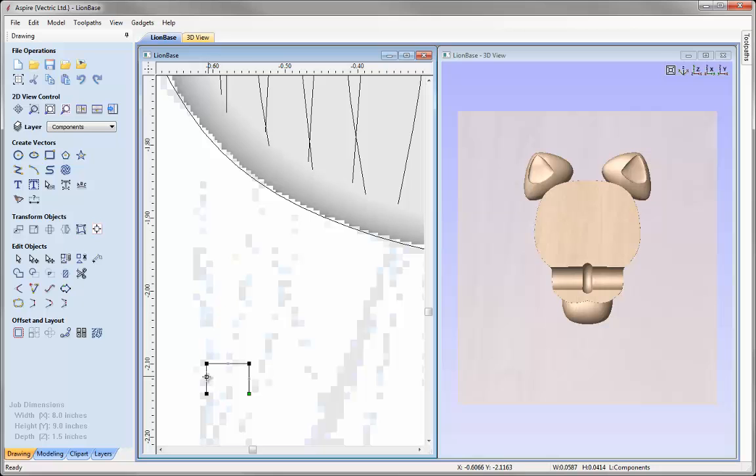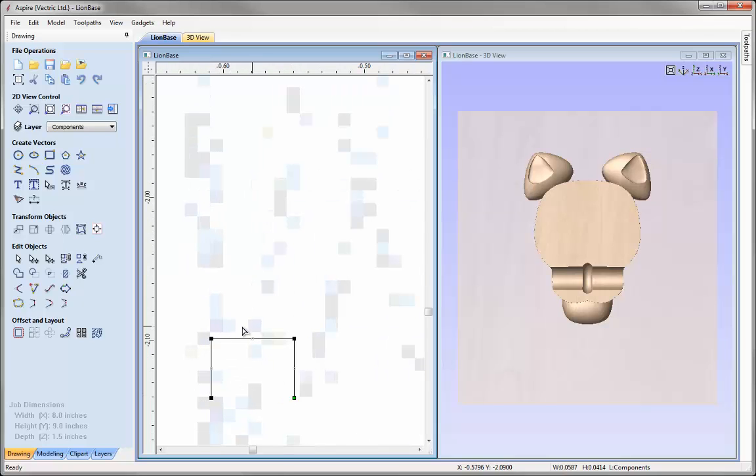Now I don't want to use this shape. I'd like to create quite a wavy shape. So what I'm going to do is just zoom in here, and I'm just going to insert a few points. I'm going to right mouse click, say insert a point, and right mouse click here and say insert a point. And then I'm going to select all of these nodes here, and I'm going to press S on the keyboard, and that will smooth them all.